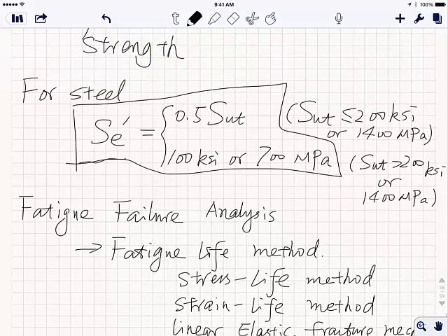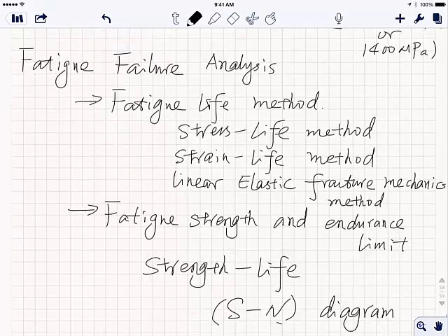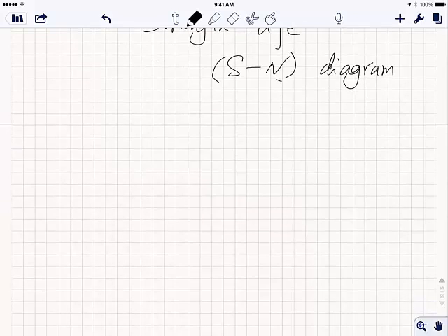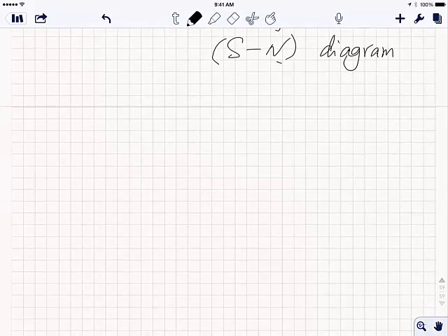Let's see next. So endurance limit is a very powerful estimation of dynamic failure. From a reality point of view, there are lots of influence factors that will also influence your endurance limit. So let's take a look at what kind of modification factors are out there that we need to consider when we have endurance limit.